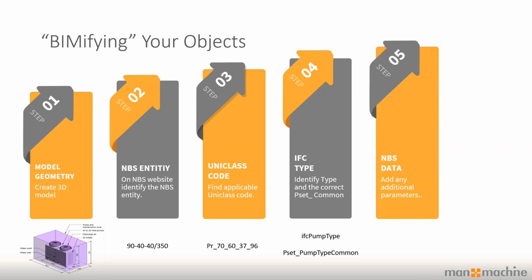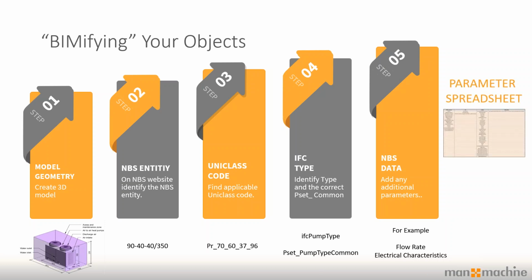We use the IFC standards to decide what it is within IFC and what properties it needs to have within an IFC, before finally adding any additional parameters that are asked of us from a level of information perspective. They basically sit on a spreadsheet.